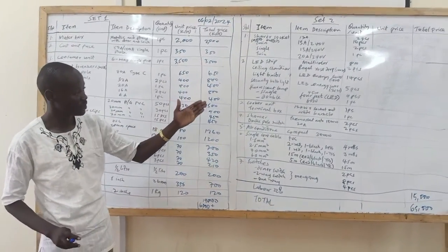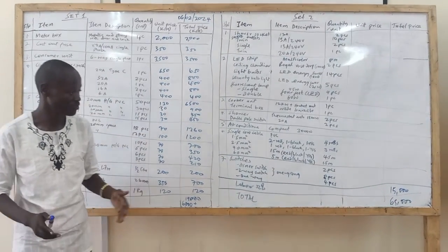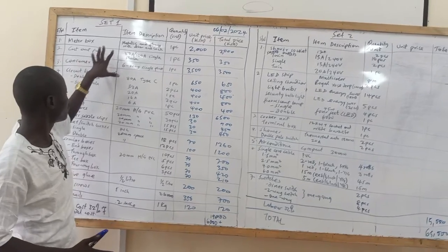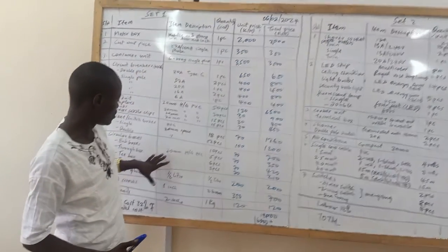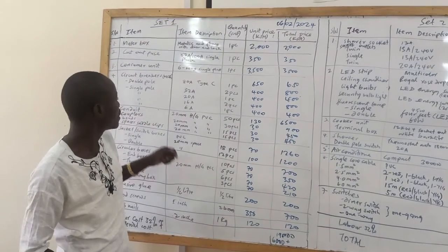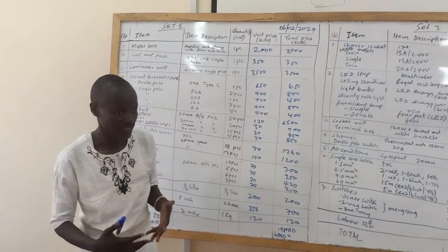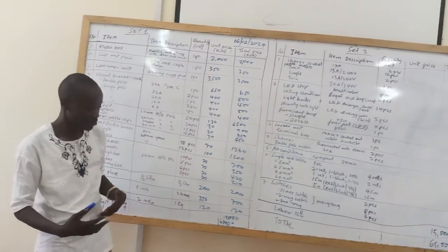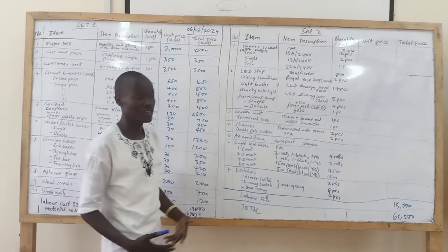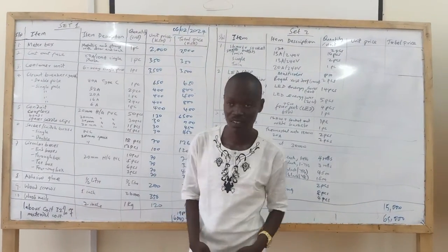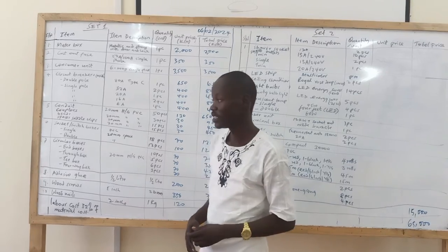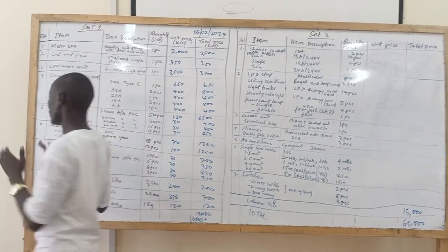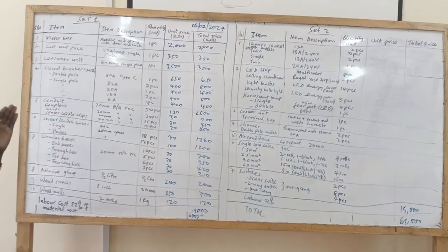So when you're preparing material tools, it's very simple. Look at the nature of material that you have. Like for this case, we are going to be making trenches. We call it chasing. We'll be chasing the walls. So we need tools. The tools that we need for chasing, we need a cold chisel. We need a masonry hammer for chase work. We also need a normal claw hammer. Yes. So once you're doing that, you already know those are the set of tools you need for day one.